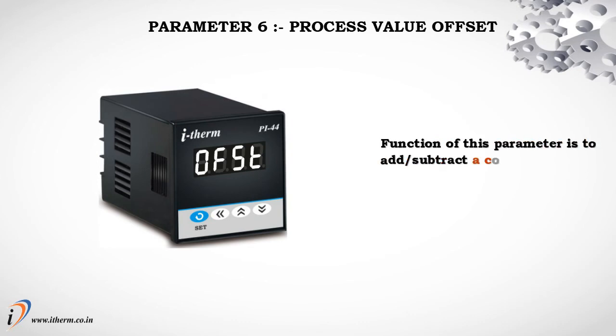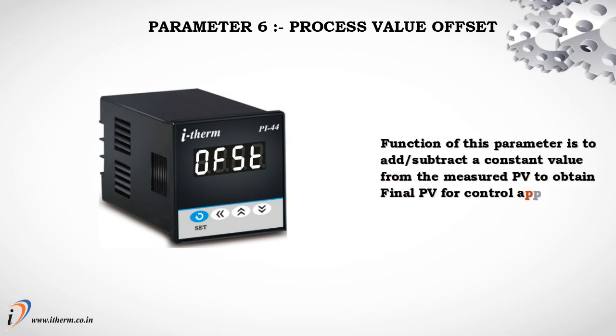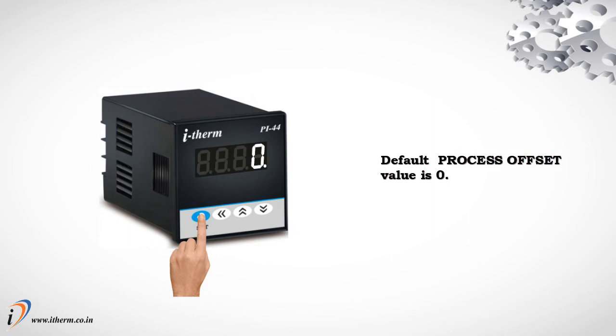Parameter 6, process value offset. Function of this parameter is to add or subtract a constant value from the measured process value to obtain final process value for control applications. Default process offset value is 0.